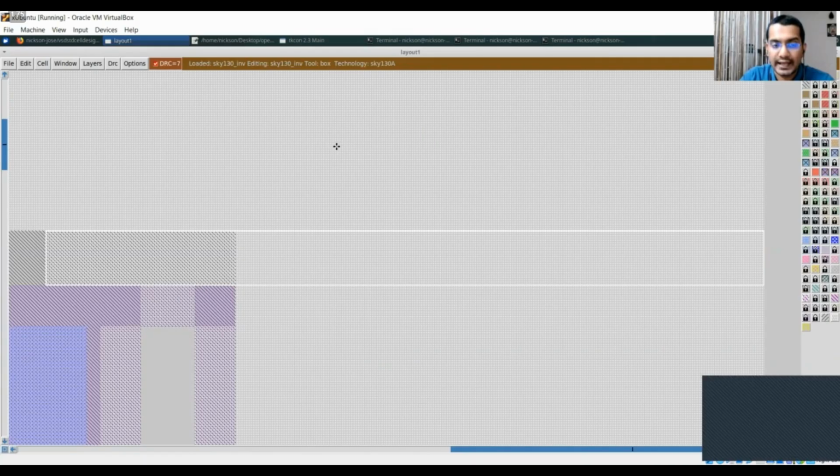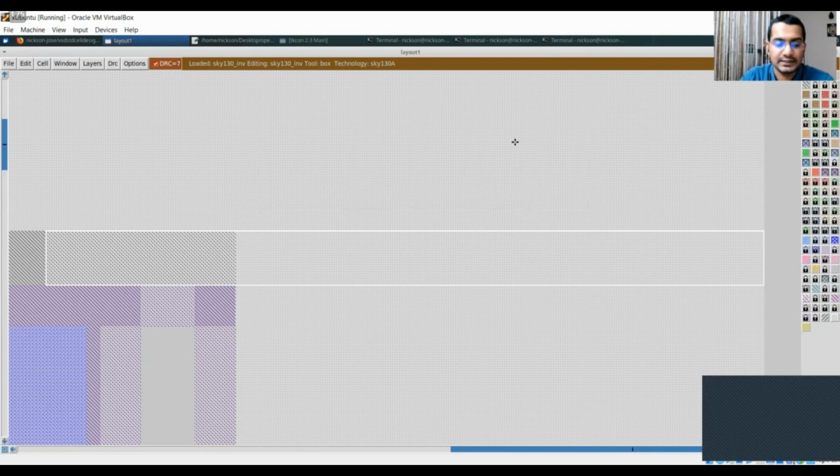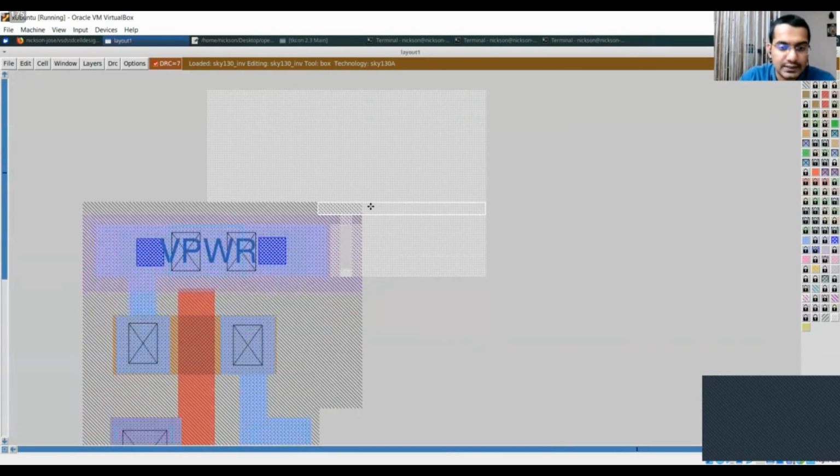And if you want to know what actually is the error, once the tool highlights this error, it will be written in the TKCon window. So these are the errors. These are the DRCs which you're seeing. This constraint, the physical DRC, is what is getting violated. This is important from the manufacturability point of view, because if the DRCs are violated, it cannot be manufactured. So you have to ensure your final design is DRC clean. So in this case, let's troubleshoot this.